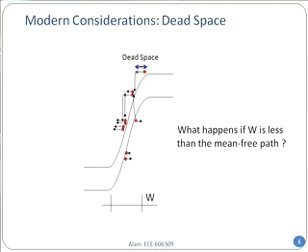Now, one thing I must explain to you, this analysis that I showed you dates back to the 1960s, when the diodes were really big, the junctions were huge, and doping was one side 10 to the power 16, another side 10 to the power 17 per centimeter cube, this type of low doping. These days, however, in modern MOSFETs, in many junctions, the doping on one side could be 10 to the power 20, and another side 10 to the power 18, huge doping. If you have huge doping, the junction is going to be very tiny, right? Very small.